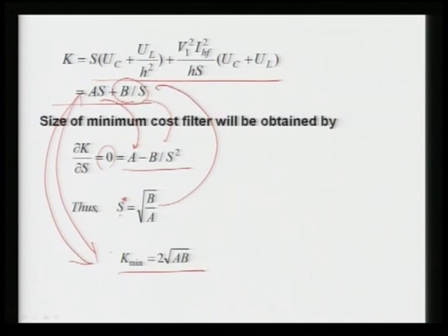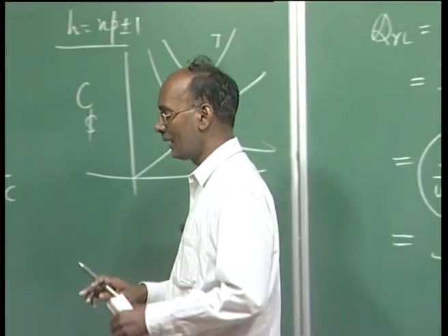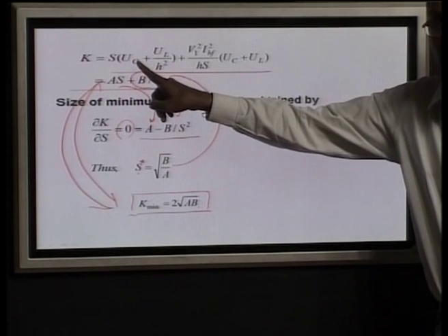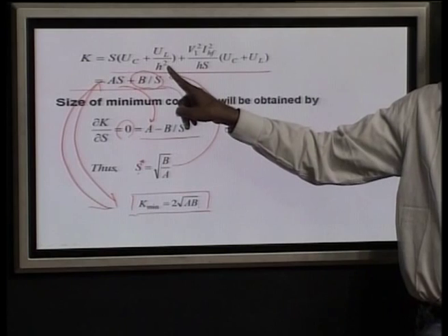So, this is basically the optimal design of the capacitor. Based on your A and V values, these values are calculated and defined. What is the A? A is basically the unit cost of the capacitor and inductor in terms of some harmonics components that are arising.